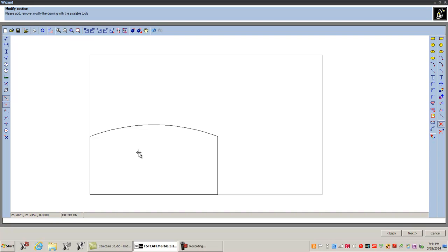Okay, they're deleted. So what we're going to do now in this example is we're going to saw this radius, okay? Now keep in mind, when we cut the straight lines or angles, we can cut the 3 centimeters in one shot. You cannot do that when the blade is rotating. It's about 3 or 4 millimeters maximum depth of cut. And again, depends on the hardness of the stone. All right.